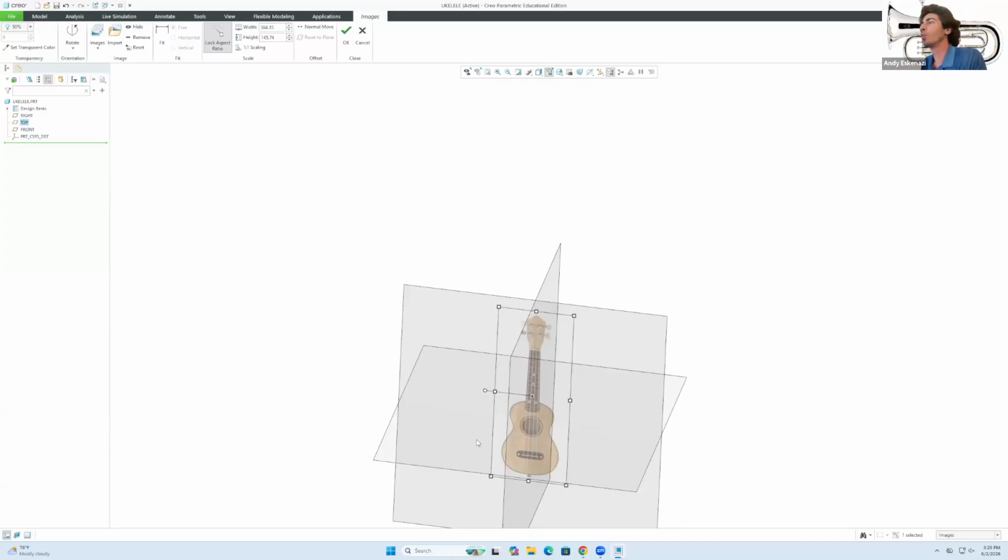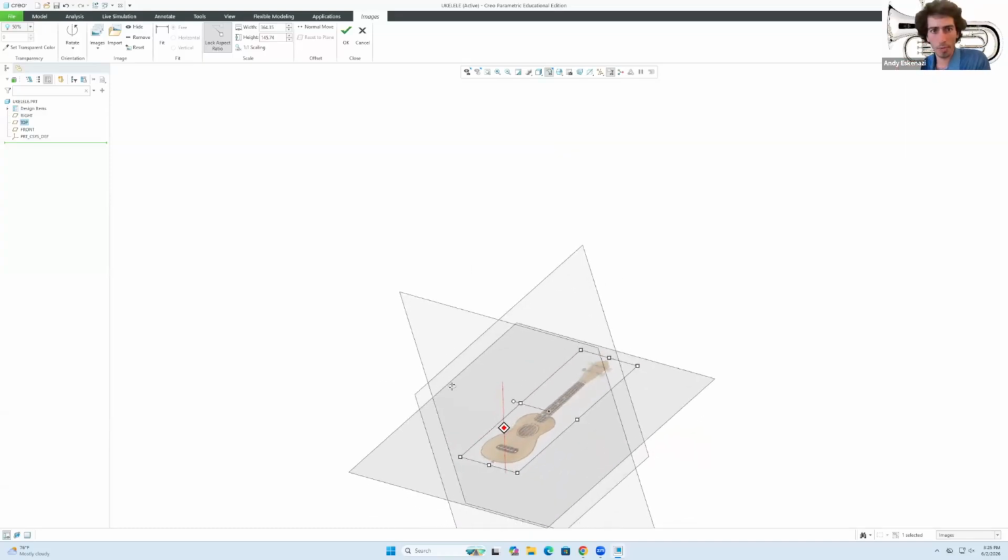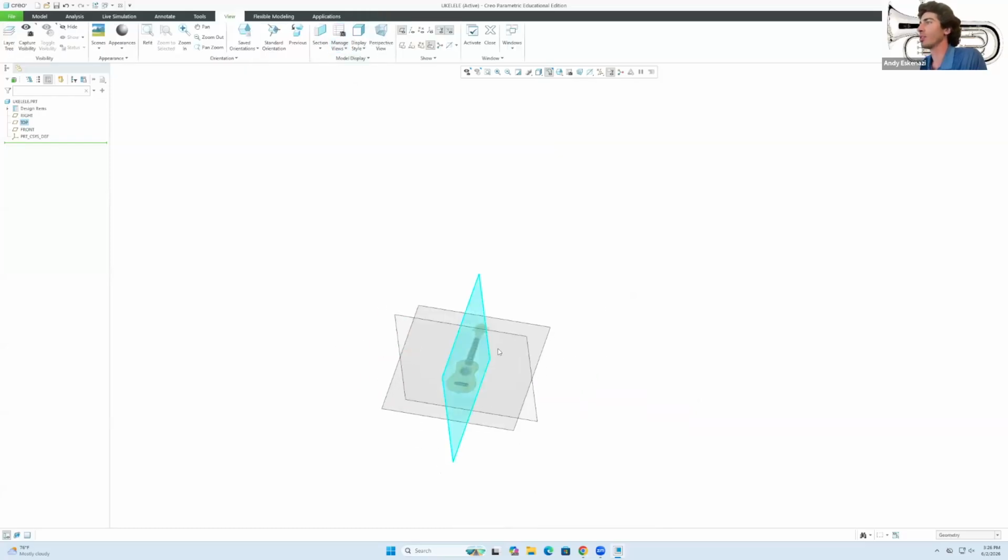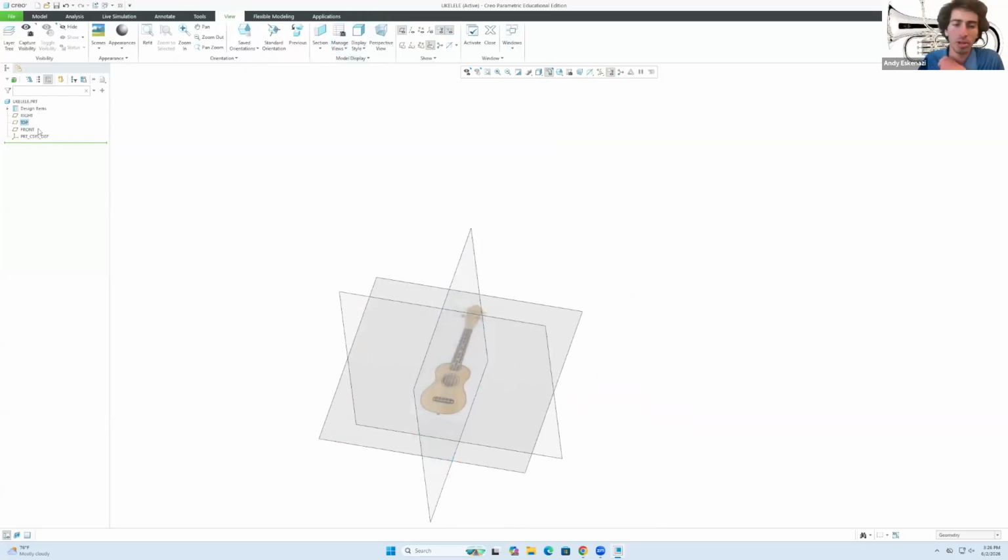The problem about using a sketch picture here in Creo, let me click OK and I'll illustrate that, is that you will see that it doesn't even appear in the feature tree. This is the area where every feature that we add would appear. This is not even a feature. It's just something about the model display. You could bring more pictures. You could potentially paste them on sides of your object as an example. But the reality, for our purposes in here, is that you'll have to deal with them kind of separately, like hide one picture if you bring another one, and so on and so forth.